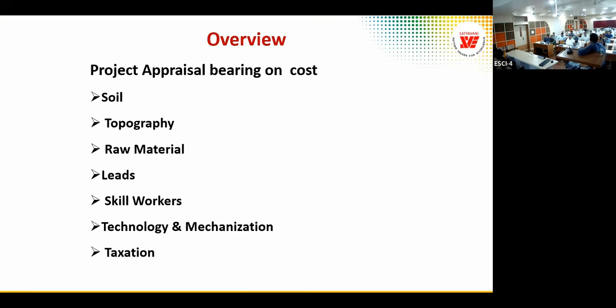Next is the topography, as I mentioned, and uncharted utilities. In fact, we have a clause in the contract on uncharted utilities. Nowadays, we have the facility to investigate all the utilities below ground. You can scan the ground to understand if there are any buried pipelines or power lines. That we have to study. So, topographic survey: I have seen some topographic survey drawings which don't even mention power lines crossing the site. LIDAR is used in this. Yeah, correct, LIDAR, for some underground utilities. For any other development, how to find out what is there below the ground, there is the LIDAR service.